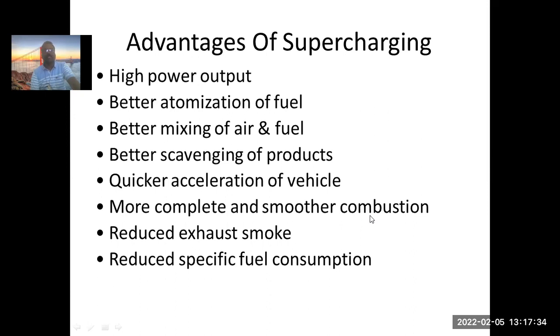Somebody unmute and tell me. Guess. How can the completeness of the combustion increase when we supercharge? Due to dense oxygen. Yes, obvious.